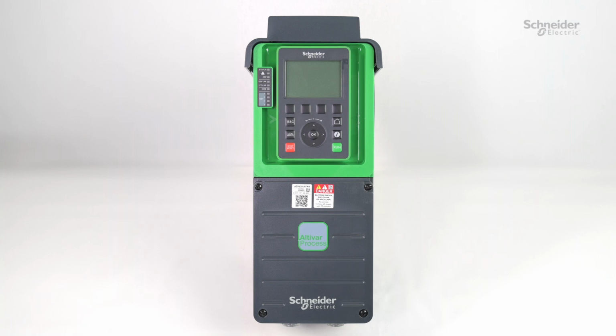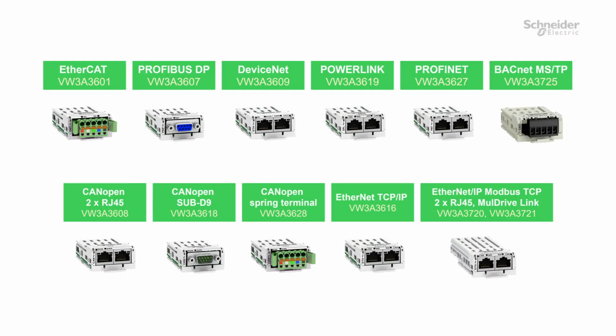In this video, we will use an ATV 600, but the troubleshooting is also valid for the other products: ATV 600, ATV 900, ATV 320, ATV 340, and ATS 480. Depending on the used field bus module, embedded or option, these errors could be triggered by the product: ETHF, CNF, COF, SLF1, or INFM. These errors are the result of a communication interruption. We will help you understand and solve these communication errors.